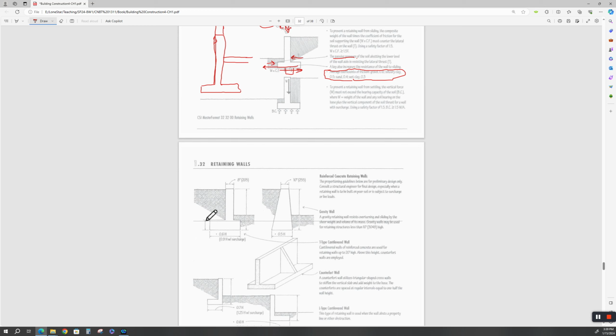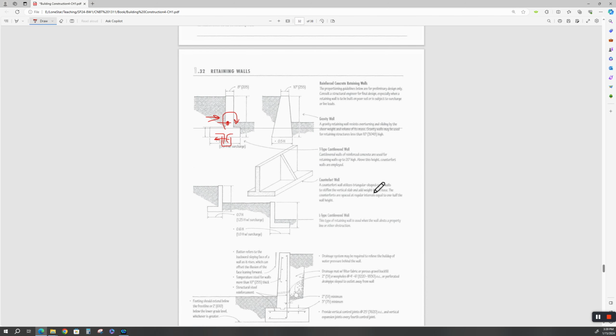And the forces over here make it want to go what direction? Makes it want to go that direction, this direction. And it makes it want to do what? Rotate over. There's the moment. And where was it? At 1/3 the height, right? Okay, and then we've got the resistance forces over here. And if you really want to get fancy, you could put a giant key down here, concrete in there. Here's a reinforcing steel. All right, so let's move on.